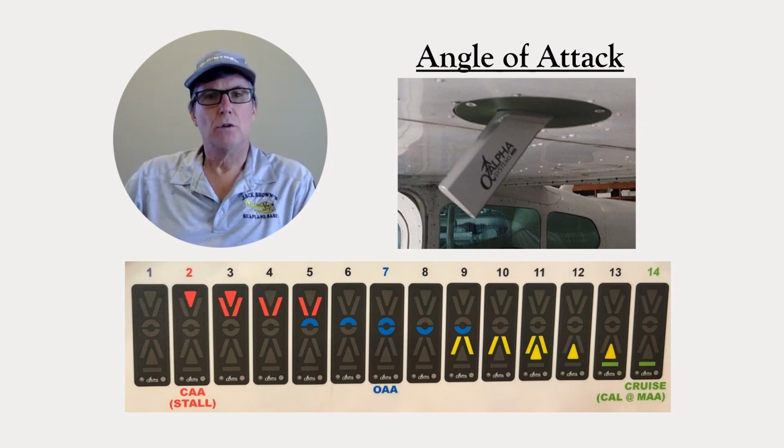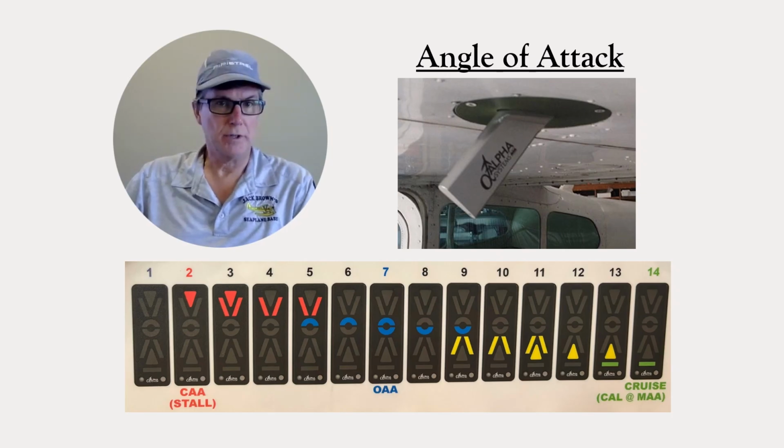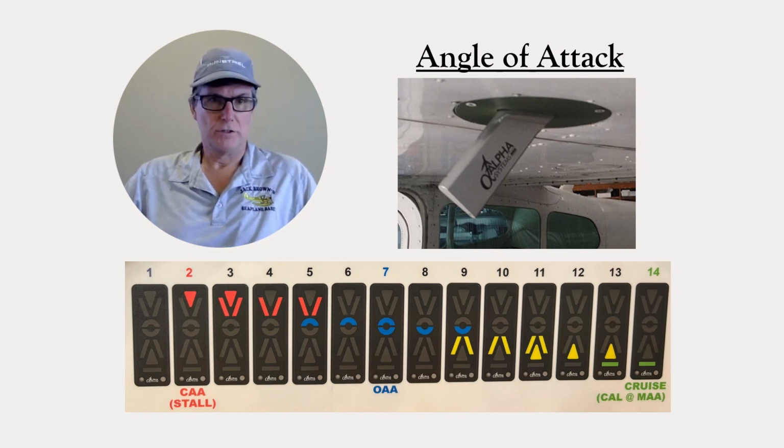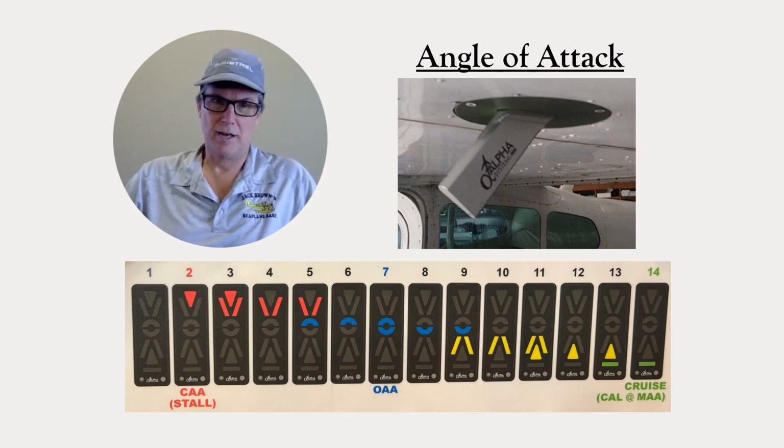Since an airplane always stalls at a particular angle of attack, but can stall at different airspeeds, angle of attack is useful information for a pilot. Using a given angle of attack for approach, as opposed to using a particular indicated airspeed, automatically corrects for changes in the aircraft weight. However, until recently, angle of attack instruments were not common in general aviation airplanes.